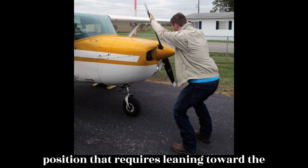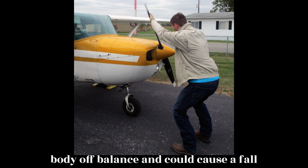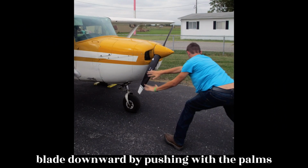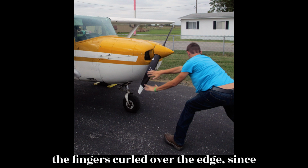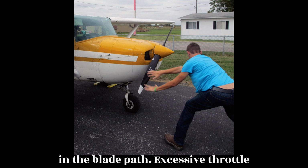Do not stand in a position that requires leaning toward the propeller to reach it. This throws the body off balance and could cause a fall into the blades when the engine starts. In swinging the prop, always move the blade downward by pushing with the palms of the hands. Do not grip the blade with the fingers curled over the edge, since kickback may break them or draw your body in the blade path.